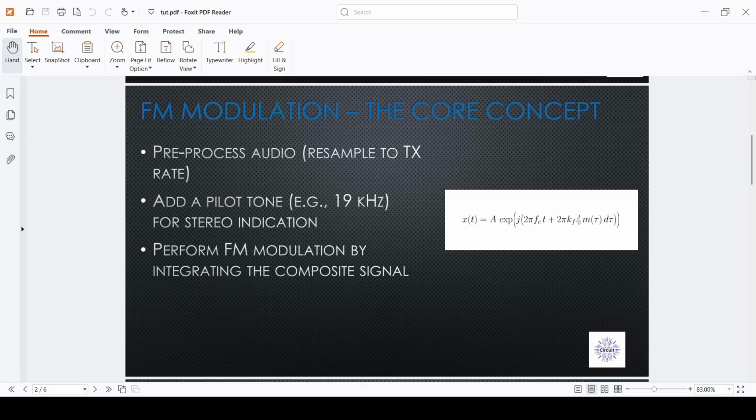So for FM modulation, what we need to do is integration of the signal we want to transmit and add that as the phase information of our signal. Let's say our carrier frequency, which is our up mixing frequency, is 5.8 gigahertz. In the baseband, we create another exponential form containing our phase, which is essentially a factor, the KF factor of our modulation, times the integration of the data that we want to send. So this is our baseband. And then after upmixing, this would be our whole data that is going to be sent.